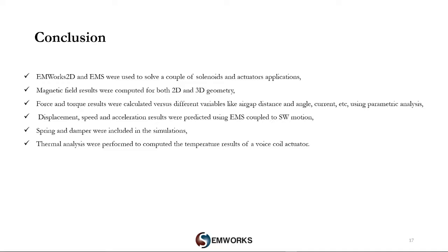Okay, now back to our presentation and its last part, which is the conclusion. So both EMWorks 2D and EMS were used to solve a couple of solenoid and actuator applications. Magnetic fields were estimated for both 2D and 3D geometry. Force and torque results were calculated versus different variables and using parametric analysis. Displacement, speed, and accelerations were predicted through EMS coupled to SolidWorks Motion. Spring and damper were included in the simulation as well. Thermal analysis was performed at the end to compute the temperature results of a voice coil actuator.